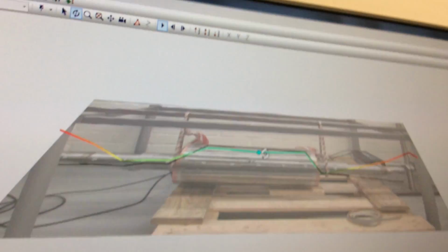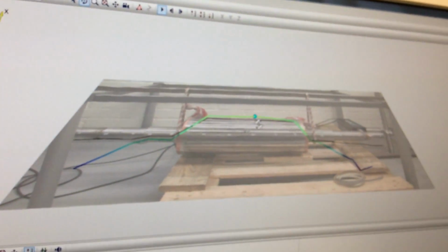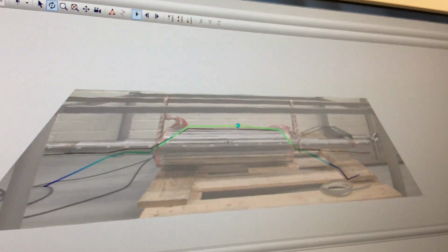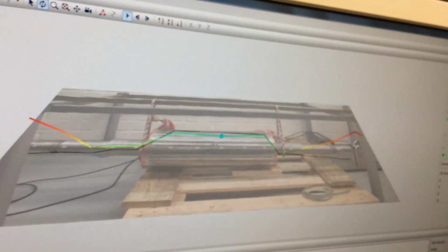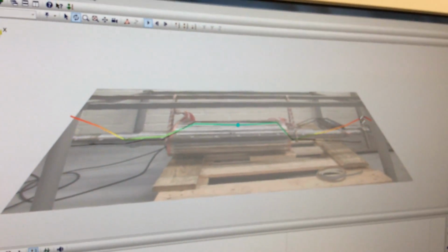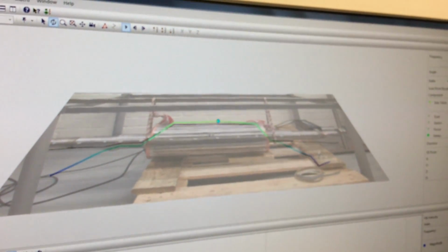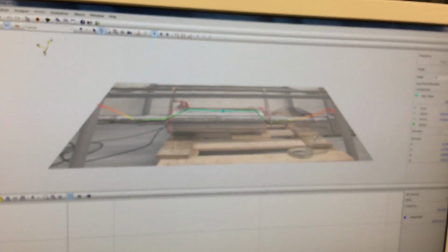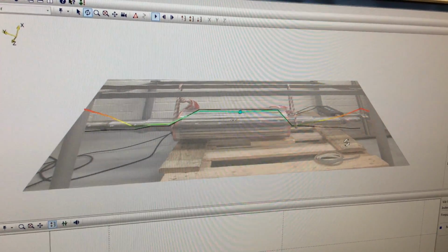And that's why having the full analysis along the whole length of the shaft is important. Then we can make an average and connect those points together, and when we plot it according to the average spectrum, the average data, we will be sure that we can detect the natural frequencies or flexible modes.